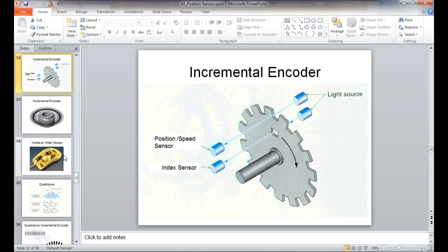It just does what? Now, using an incremental encoder, we actually have a sensor, and then we combine it with another sensor that actually counts the blades. You know, see how that works? Pretty neat. So the rate, how fast, the frequency of these things coming by, that would give us an indication of what? Speed, but it doesn't tell us direction.